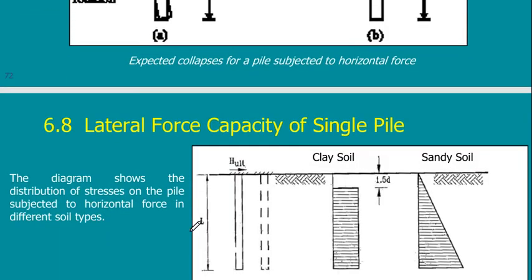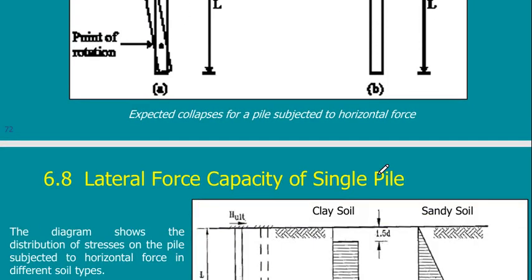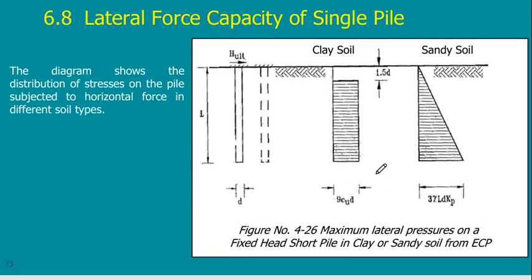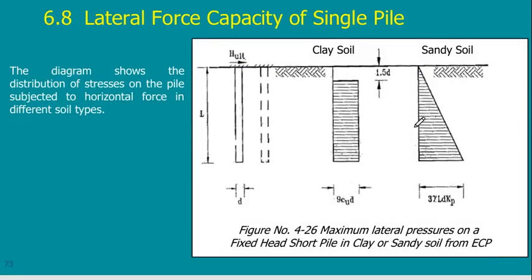This ends our calculations for the piles as a single pile. This is just for info, how to know how piles will behave in case of lateral load. You just need to know it. It depends on the stiffness of the pile. Will it act as one body, or will it have a bending inside it because it is a very long pile? It also depends on the type of soil.